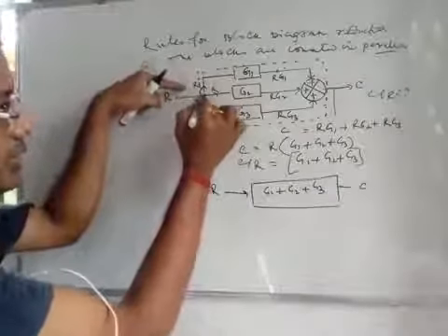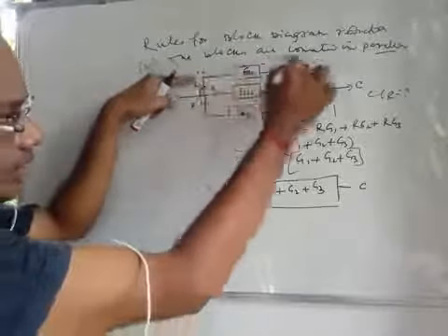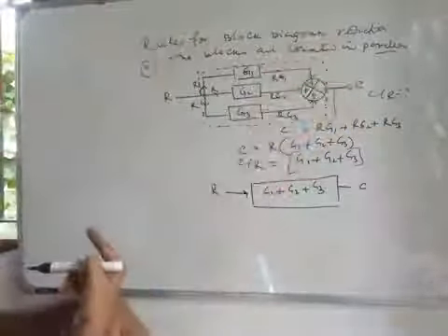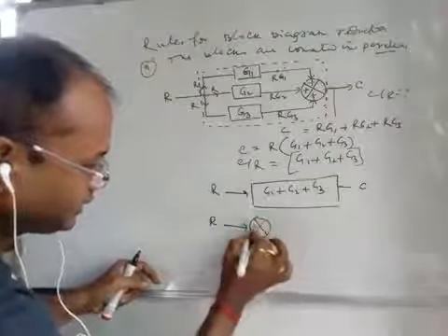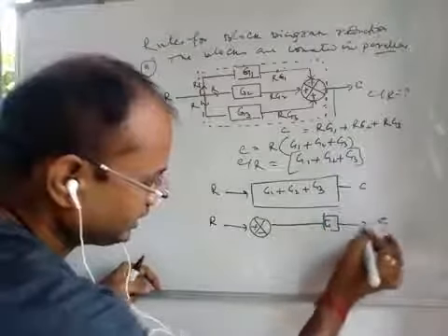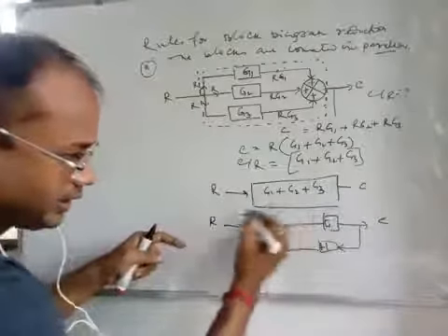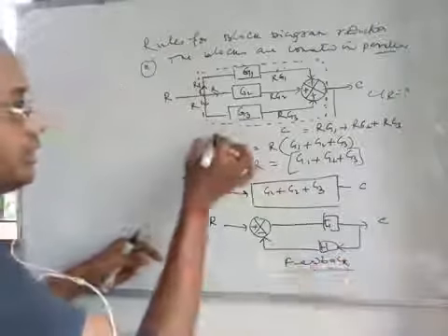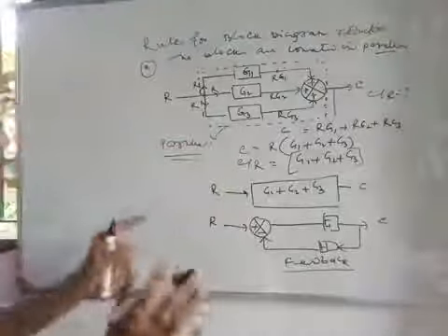The branching, note the branching, all the signals are dividing. That means branching from this point and they are coming back to a certain point, not that the signal direction is changing. So in case of feedback, what happens? The signal going in this direction comes back via this block to this direction. This is your feedback, right? And this is your parallel connection. So there is a distinct difference.